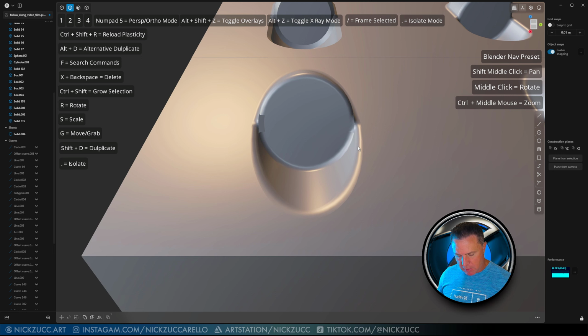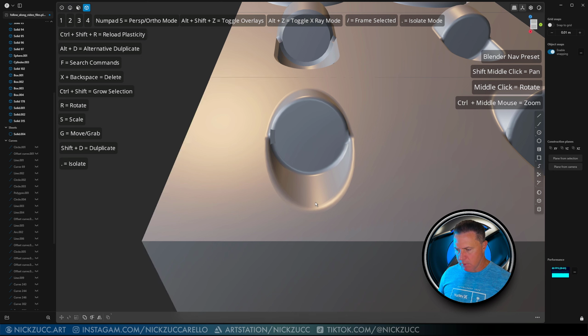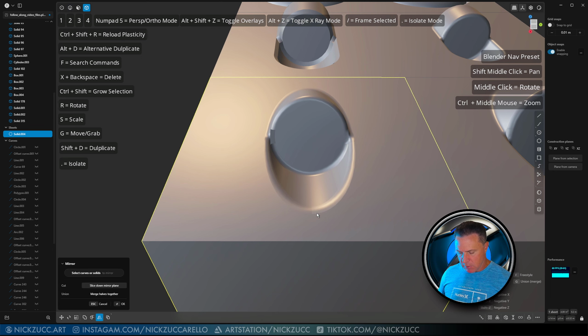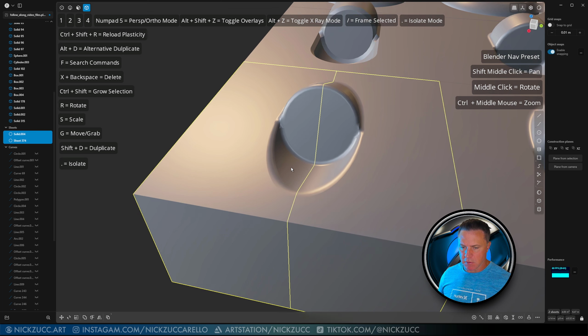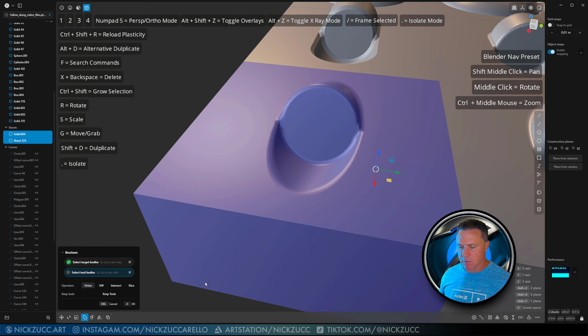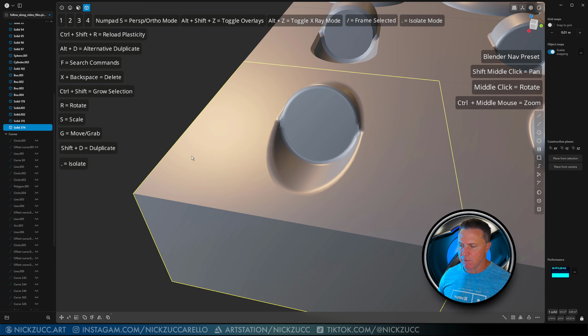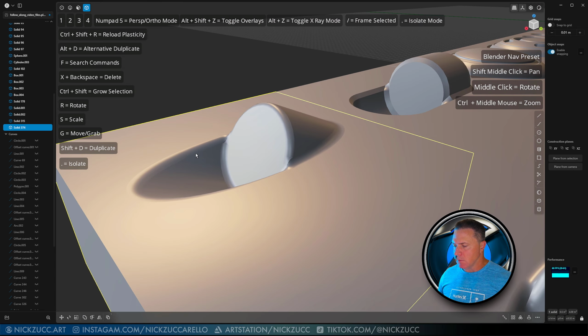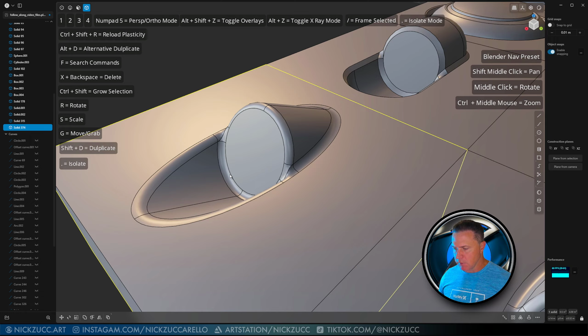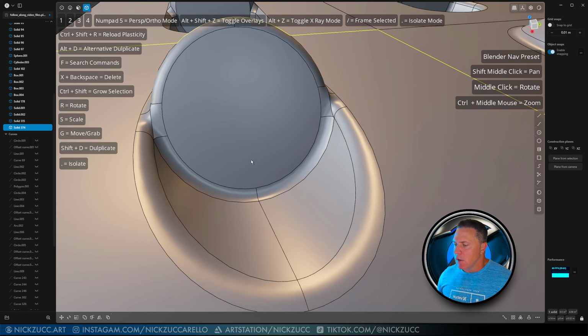So I'll select this, I'll hit Alt X on the object mode, and then tap F, and then find a center point, and then come straight across like that. And we've got this and this. I forgot to merge the 2 pieces, so I can just tap QQ to join them together like this. And if I've done everything right, it should turn that into a solid on there. So let's look at the wireframe on this again.